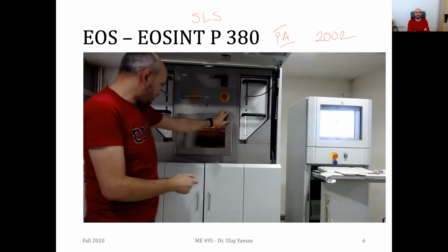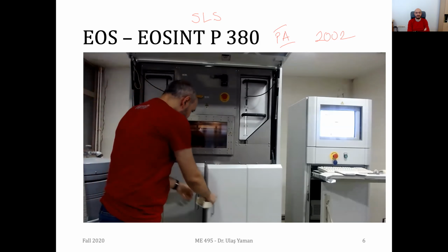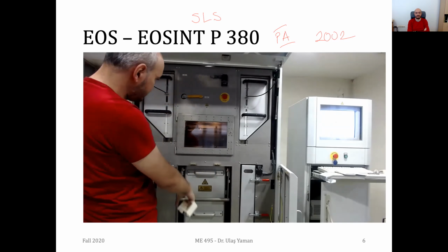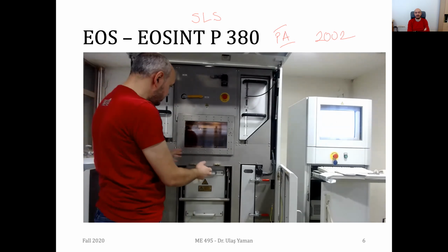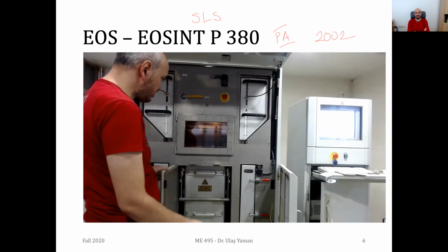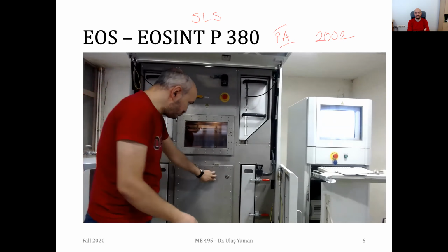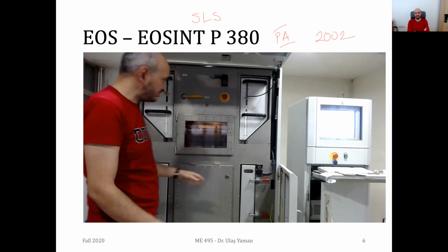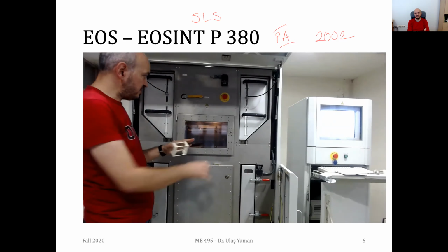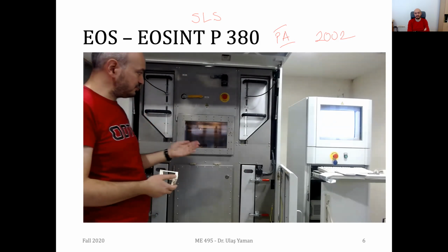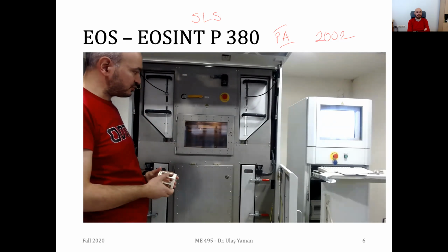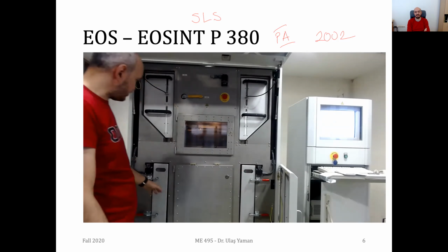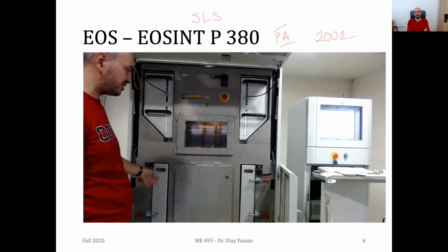And we have other equipment. There's another heater here, which increases the temperature of the powders in the bed. And then we have two recycling units, one on the left, one on the right. Since you have many powders around which are not used for the fabrication of the product, they are stored in this right recycling tank and the left recycling tank.